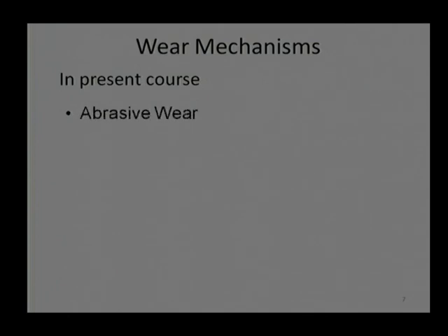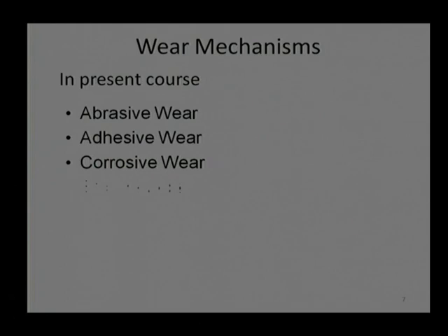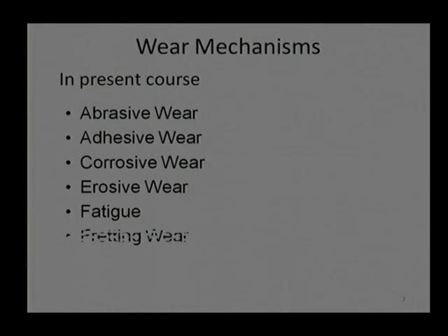However, wear itself is a complete subject, and we would require maybe 40 to 45 lectures on wear. We do not have that much time. So, what we will do is try to cover wear in 4 lectures, and basically we will cover abrasive wear, adhesive wear, corrosive wear, erosive wear, fatigue wear, and fretting wear. These important topics will be covered. The remaining topics can be derived from these basic mechanisms, like the number of subdivisions under abrasive wear, which can be treated in a similar manner; only the coefficients and parameters will vary to some extent.